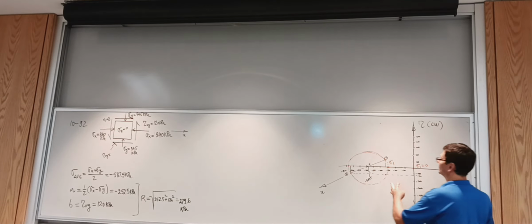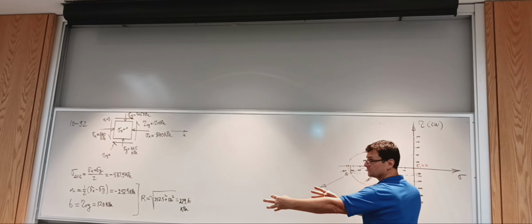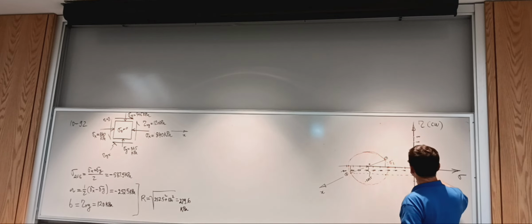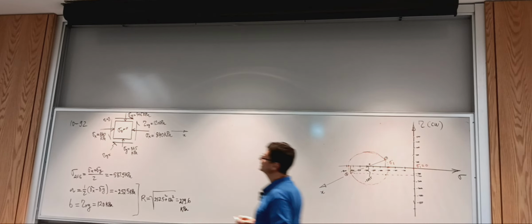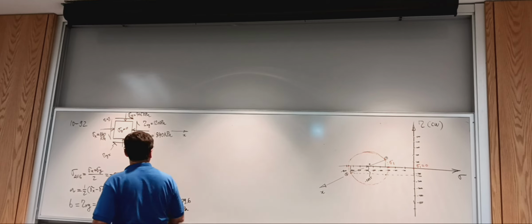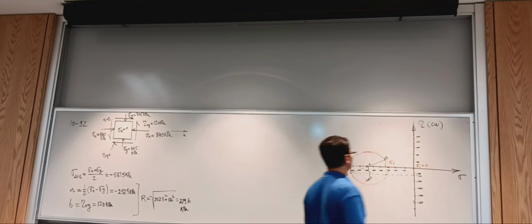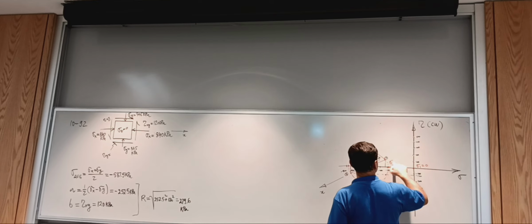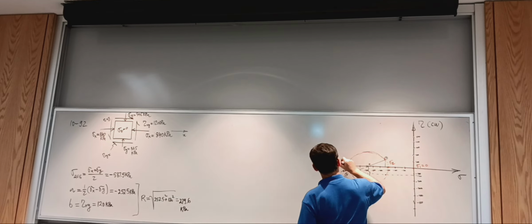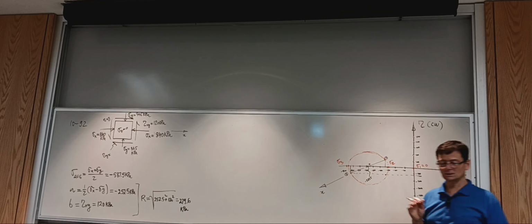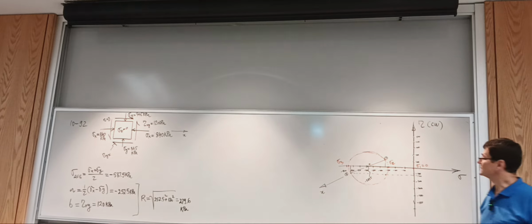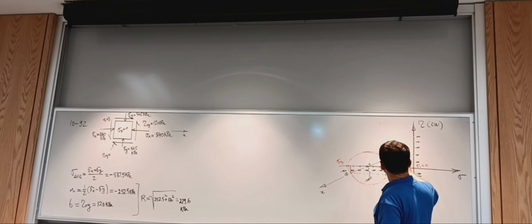When the 2D circle is all the way to the left or to the right, I need to consider the zero stress, which is sigma z. That's helpful to evaluate the true maximum shear stress. So this will be sigma 2, and this is sigma 3, which is the smallest, with their sign, of the three stresses.